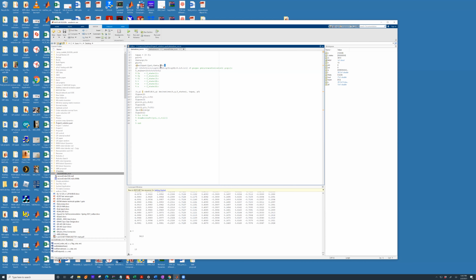And the next step is important. Since we are performing the Quaternion integration, we need to take these initial yaw, pitch, and roll values and convert that into the initial Quaternion. So I use the command eul2quat. This will convert Euler angles to Quaternions. And please note, by default, this is Z, Y, and X. So this is Z, this is Y, this is X.